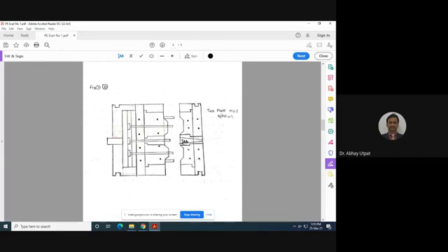Once solidification starts, cooling will start. So closing of mold, injection, cooling, solidification, opening of mold, operating the ejector mechanism, and ejecting the component. These are the steps in the injection molding process.